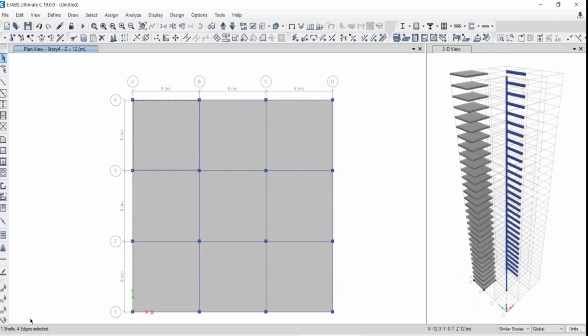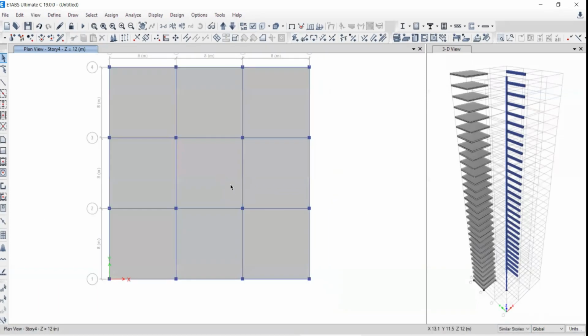Once it is in selection, actually, there is no any pair. There is no similarity. There is no grouping that we did in the last case. Okay. So that's why you have to check it. In this way, you have to use these one story, all story and similar story options. It will help you a lot for doing the modeling in a very fast way. Your modeling will become very easy if you are effectively going to work with this one story, all story and similar story option. Okay. So we'll practice with this in detail in upcoming sessions.